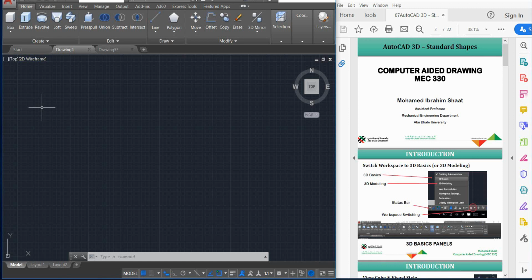The concept of any software, I'm talking in general, the concept of 3D modeling in terms of science, which is not necessarily specific here. I'm not talking about AutoCAD. I'm not talking about a special software like SolidWorks or whatever. Any solid software used for 3D modeling works with the same concept: in terms of computational 3D modeling, we cannot build a 3D model at once. We have to create a two-dimensional sketch first. Then we're going to convert this two-dimensional sketch into a 3D solid.